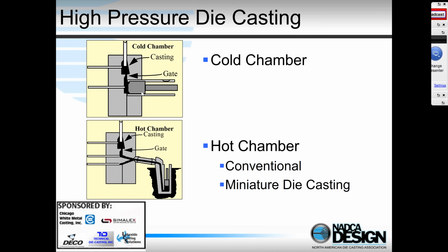Again, we have this large diameter cylinder, somewhere between 3 and 6 inches inside diameter. That's called either a shot sleeve, or sometimes a cold chamber, which is where the name comes from. We pour the liquid metal through a hole into the shot sleeve, as we showed on the previous schematic, and then this hydraulically activated plunger moves forward to inject the liquid metal under very closely controlled conditions into the die cavity. The die cavity is shown here in this schematic.